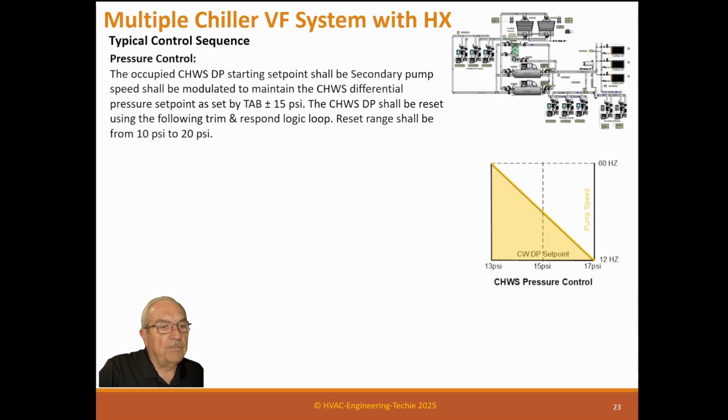And so if the pressure is at 17 psi, our pump is down at 12 hertz. When it gets to 13 psi, it'll be at 60 hertz. And this is the loop inside that runs the pump. This is the loop that runs the pump.